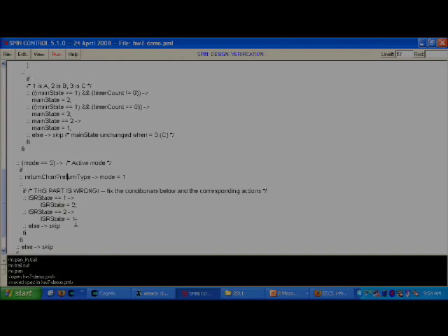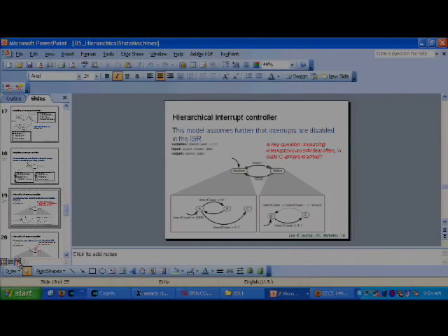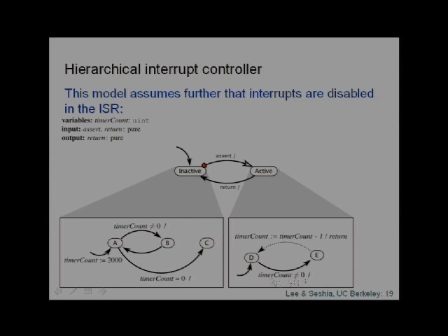So basically, the state machine that we have here is just this: from D you go to E, and from E you go back to D. And that's obviously not the machine you have there. Here you have a guard, timer_count not equal to 0, and an associated action plus an output. This output will correspond to writing a value on the return channel, and this action corresponds to decrementing timer_count.